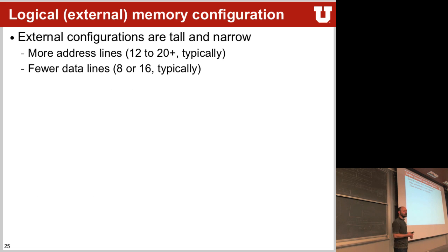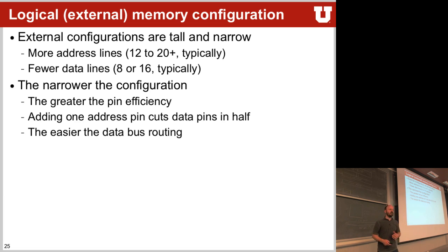Okay, external memories. Well, external memories are most of the time tall and narrow. So internally, we have squared because it makes it more convenient for our chips themselves. If we have them external, we actually have them in a different architecture, tall and narrow. And the reason for this is because we can then change the number of pins it needs to access this particular chip. Remember, we only have a limited amount of pins and I/O interfaces that we can interface with. So we want to reduce that particular amount.